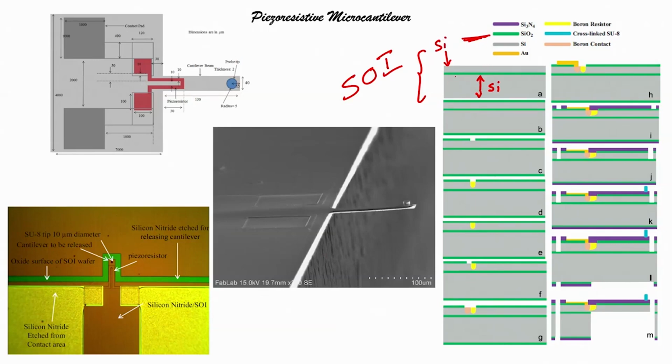So, this top silicon is on the oxide material, that means silicon on insulator, insulator is our SiO2, silicon is the top silicon. So, you can see that the silicon on insulator, right, this is our starting substrate, right,